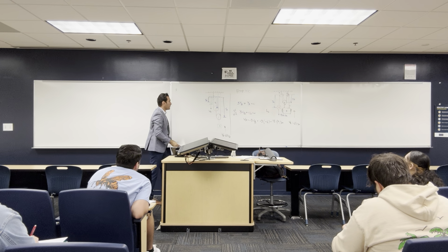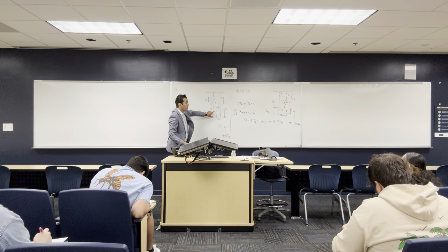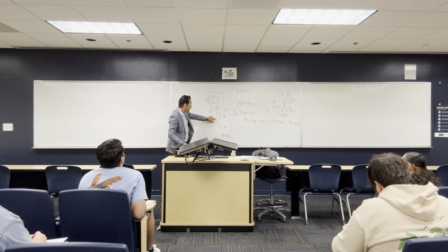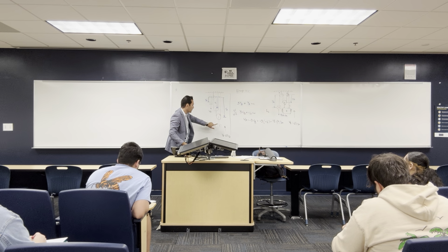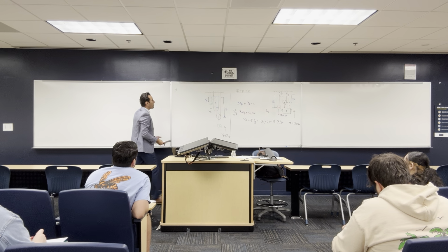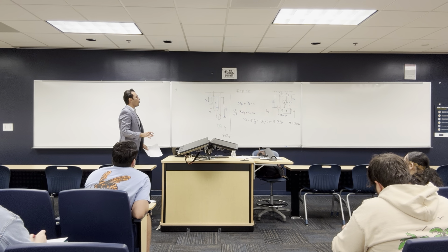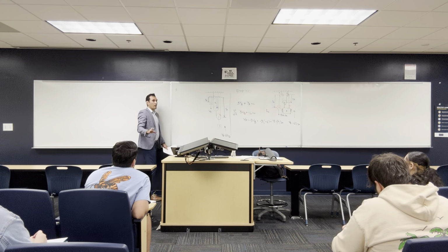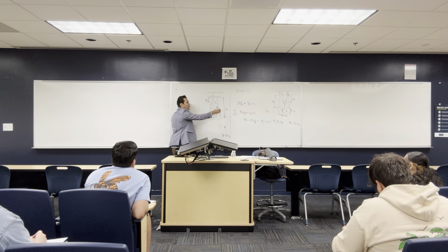That's the moving part. I have this can move up and down. I have this can move up and down. And this weight A can move up and down. You're gonna say, but B also is moving up and down. Since I already included this pulley, this B has the same velocity as this. So basically I can say that the velocity of this is the same as the velocity of this. How about you guys tell me what equations do I have here? First, give me an equation of the red cord.